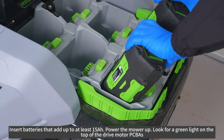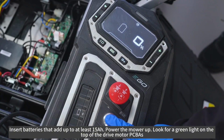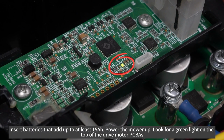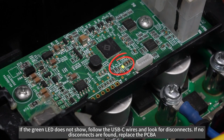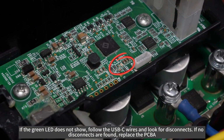Insert batteries that add up to at least 15 ampere-hours. Power the mower up. Look for a green light on the top of the drive motor PCBAs. If the green LED does not show, follow the USB-C wires and look for disconnects. If no disconnects are found, replace the PCBA.